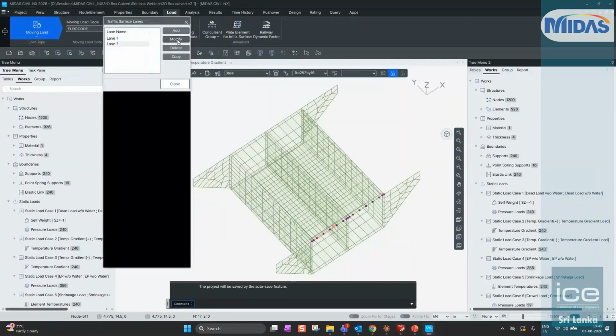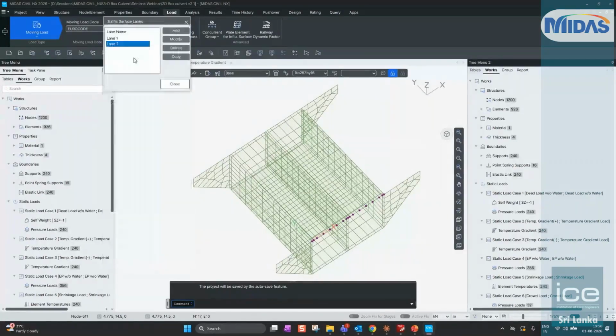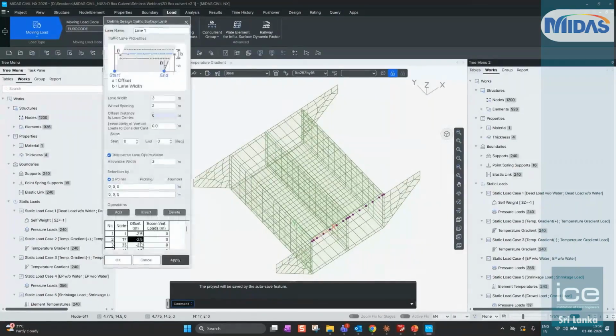Okay, now moving to the other lane as well. So again, you have defined the two lanes. This is an offset of 7 meters. Earlier you had an offset of 2.5 meters defined. I have used some arbitrary values for calculation of 2.5 meters. You can update this value as well. Now the other lane that I have defined is at an offset of 7 meters, adding the half of the other width as well, from the lane.